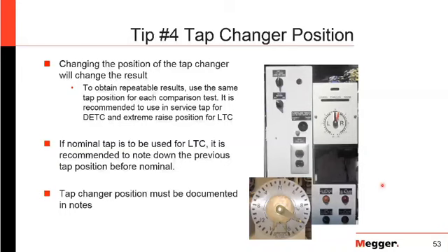The next thing, as I mentioned once again, your connections will influence the result. So bad connections can actually vary the result too. If you look, this is actually the same transformer taken at two different times, and it's the same phase, it's the same measurement, X1 to X3. So we energized on the X1, measured on the X3, and everything else is open. But you'll see there's a large deviation here in the very high range frequencies.